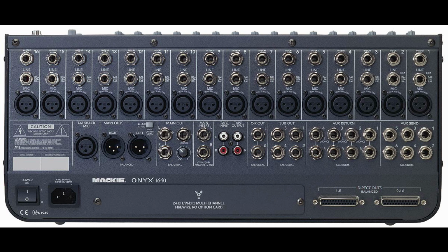Some of the speakers may be using TRS. Depending on the mixer or console, some provide TRS output, so you may use TRS connections. And also you need to check the input of your loudspeaker. If the input of your loudspeaker requires 1/4 inch, then you'll be using a 1/4 inch cable. If the input of your loudspeaker requires XLR, then you are going to use an XLR cable.